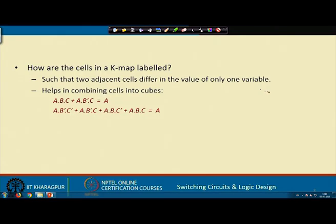So, the number of literals goes on decreasing as we make the cubes larger and larger. Suppose originally I have an n variable function. If I make a 2 cube, it becomes n minus 1. If I make a 4 cube, it becomes n minus 2. If I make an 8 cube, it becomes n minus 3, and so on. So, the terms will become smaller and smaller. Okay.